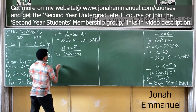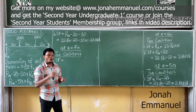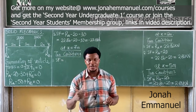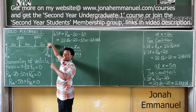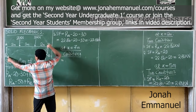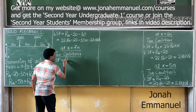Condition 1: shear force is equal to all the forces before that point. Where is my point? Here. What are the forces before here? Before here, I have 3 forces: 1, 2, and 3. This one is going up, so it becomes RA positive.